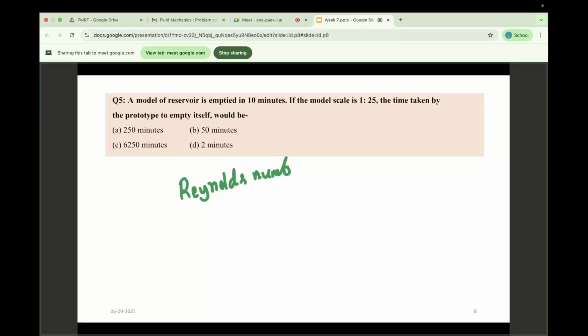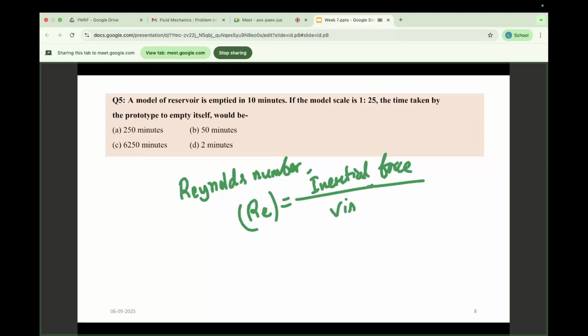Reynolds number. So this Reynolds number, say it is represented by Re. It is basically the ratio of inertial force by viscous force. Okay. So you will always find this formula, I think you have seen this formula, rho VL by mu or rho VD by mu. This formula you find. So why is this thing quite essential? See, it is the inertial force by viscous force. That means here viscosity plays a vital role, right?